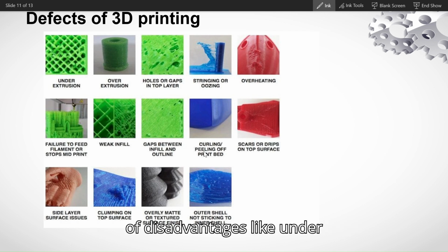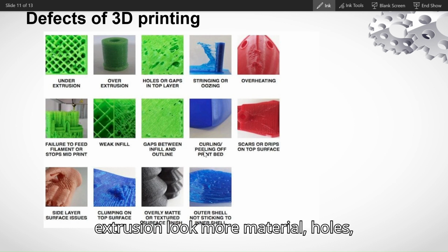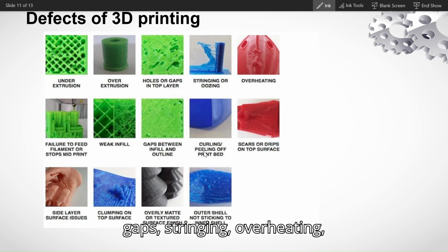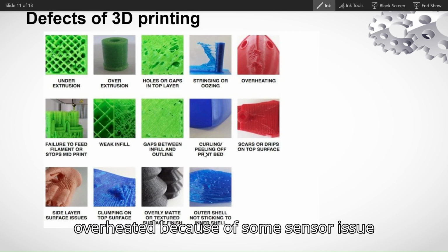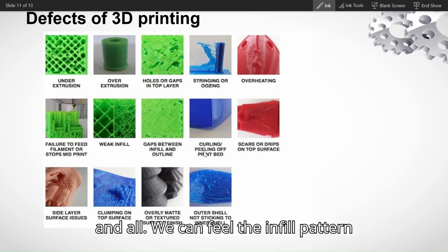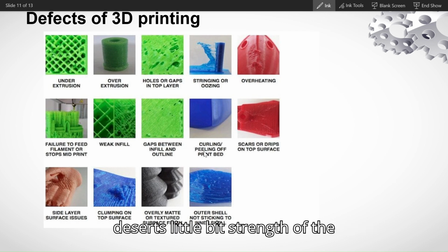There are a lot of disadvantages, like under-extrusion, which is a lack of material, over-extrusion, which is more material, holes, gaps, stringing, and overheating, maybe because of some sensor issue. We can feel the infill pattern decides the strength of the material. Also gaps between infill and outline, curling, warpage, etc. So these defects will be there.